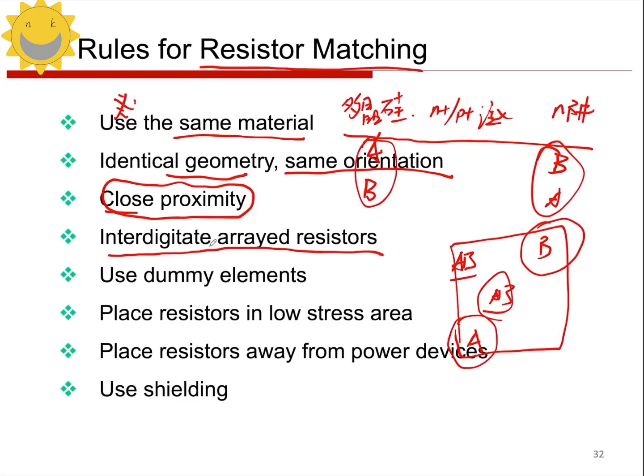The next point is to arrange the resistors in a forked layout. The reason I didn't mention the supply line here is that generally, resistors are long and narrow, and we often draw them in a serpentine structure. So, it's more suitable to use this forked structure for axial matching. You also need to pay attention to using large devices, right? These large devices must be utilized.